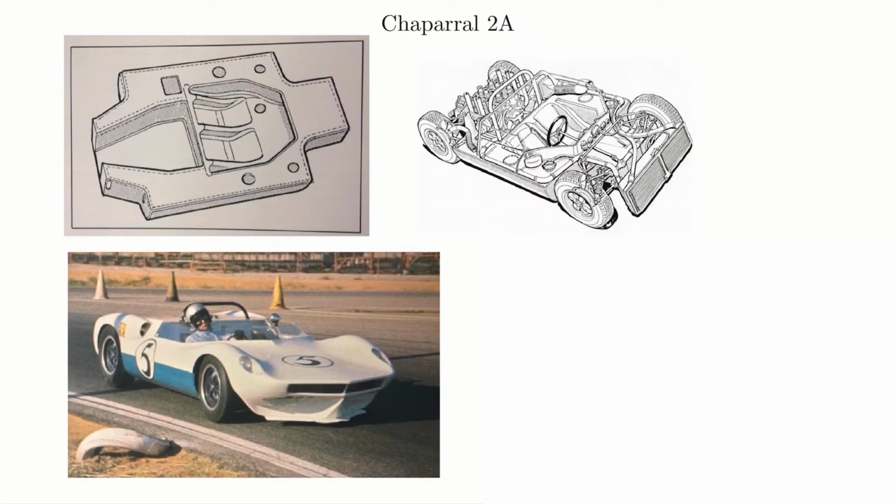Now, of course, this came with some unexpected downsides too. They'd taken the engine from the front and put it in the rear, and they'd also lightened the vehicle with this fiberglass chassis. So you can probably guess what the first problems were on this vehicle. When the front is really light, and they hadn't mastered aerodynamics yet, now you're getting a lot of front end lift, and what's known as understeer.